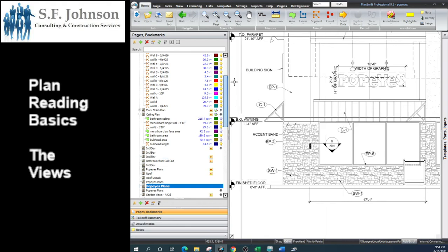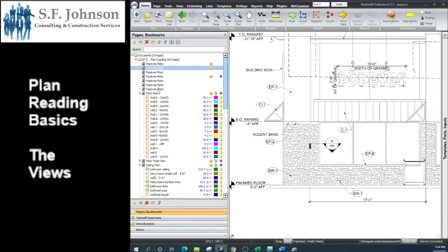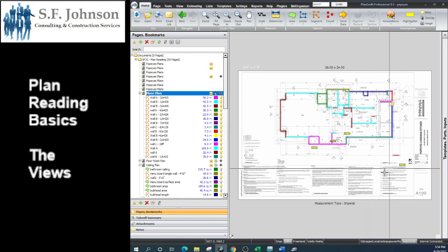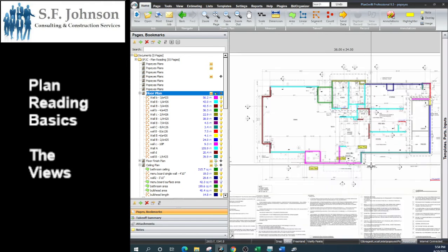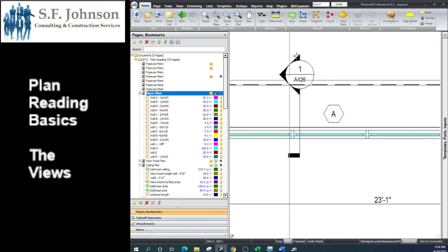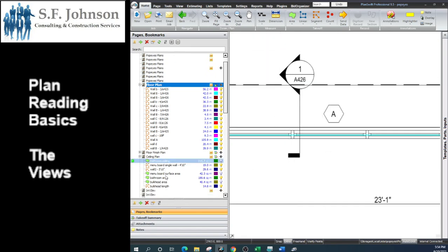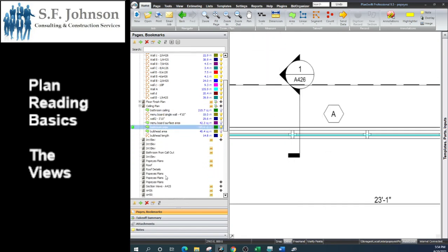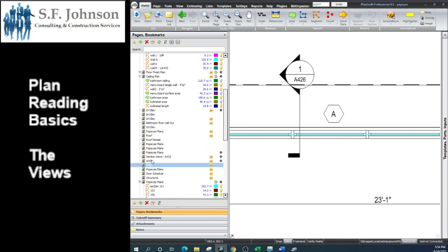Okay, so that completes the 4 views. You have the plan view, the most basic of the views from above. Right? It's the view from above, most basic of the views. What we see the most is the floor plan. From the floor plan, of course, we're measuring how many linear feet of wall, but we need a height for the wall. So the section view takes us to the height. Okay, so that's the second of the views, which is the section view.